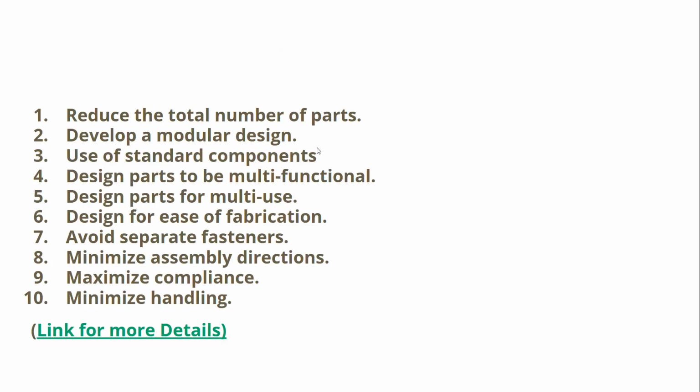These are some parameters. Reduce the total number of parts. Develop a modular design. Use standard components. Design parts to be multi-functional. Design parts for multi-use. Design for easy fabrication. Avoid separate fasteners. Minimize assembly directions. Maximize compliance. Minimize handling.